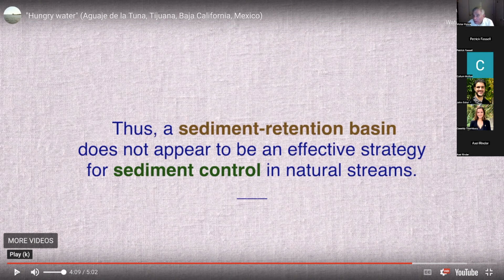Is there any other solution? Well, you can figure out what solution, but do not contradict or go against the Lane relation, which is a statement of practice. Unfortunately, the Lane relation, well respected among sedimentation engineers, is not well known among civil engineers or architects for that matter. Architects practice a lot in various places. And one of the problems with this particular project was that the design was done by architects and perhaps hydraulic engineers that were not sedimentation engineers. They did not know in 1991, when they did this project, of the existence of the Lane relation.